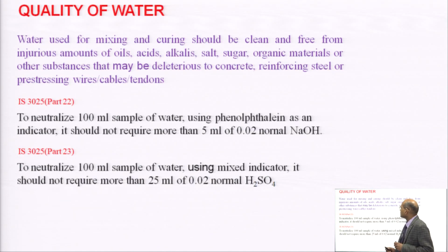Okay. So, now we will discuss quality of water. Quality of water is very important, because strength of concrete depends on the quality of water. So, water used for mixing and curing should be clean and free from injurious amounts of oils, acids, alkalis, salt, sugar, organic materials or other substances that may be deleterious to concrete, reinforcing steel, pre-stressed tendons, wires, cables.